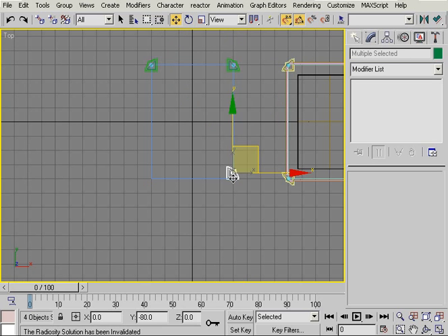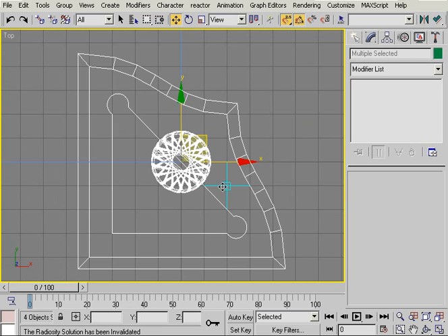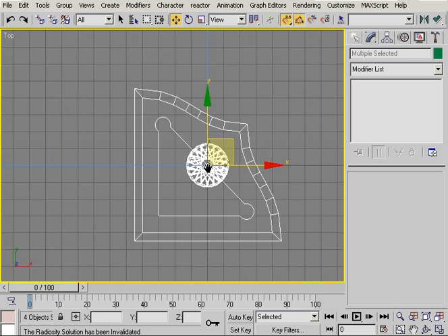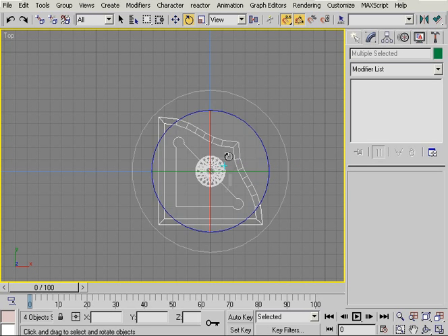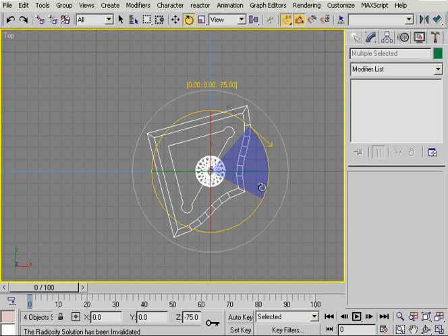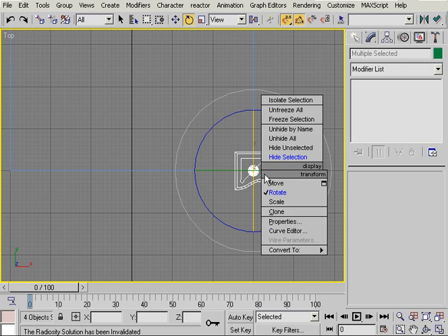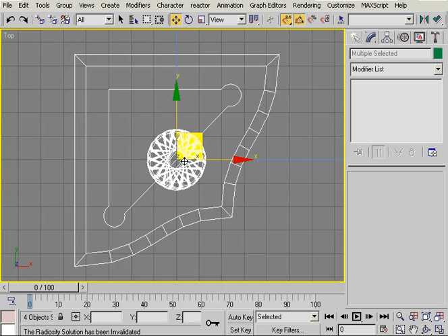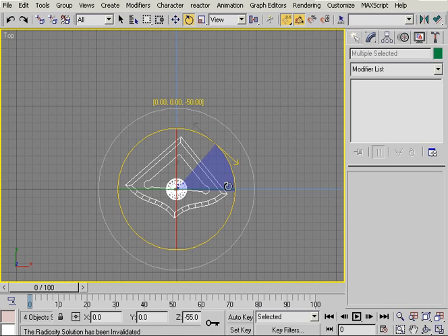And I'm going to press shift and go down again. Now I have to make sure that I'm snapping to the proper point, which is the center of the cylinder, snap to the corner of the rectangle. And then I will rotate again by 90 degrees. And the last one over here, zoom over. Okay, the snap is good, and I'll rotate again.